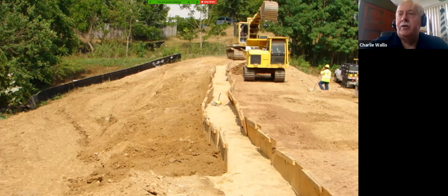Now we're getting close to the surface of the dam, and you can see that the filter diaphragm can be quite large. You'll have your spillway pipe, and then it extends quite a bit of distance on each side as has been designed. And this also needs to be compacted. You can see a compaction test is occurring here on the filter diaphragm material.